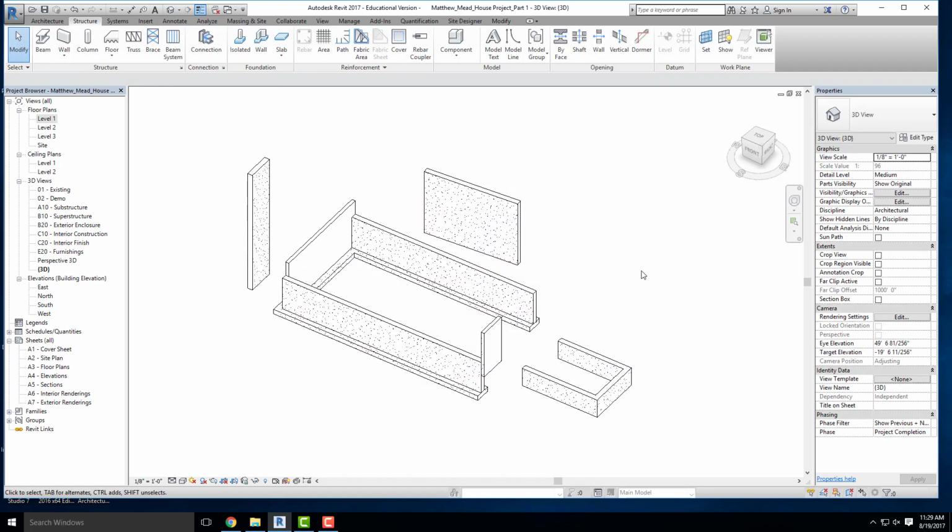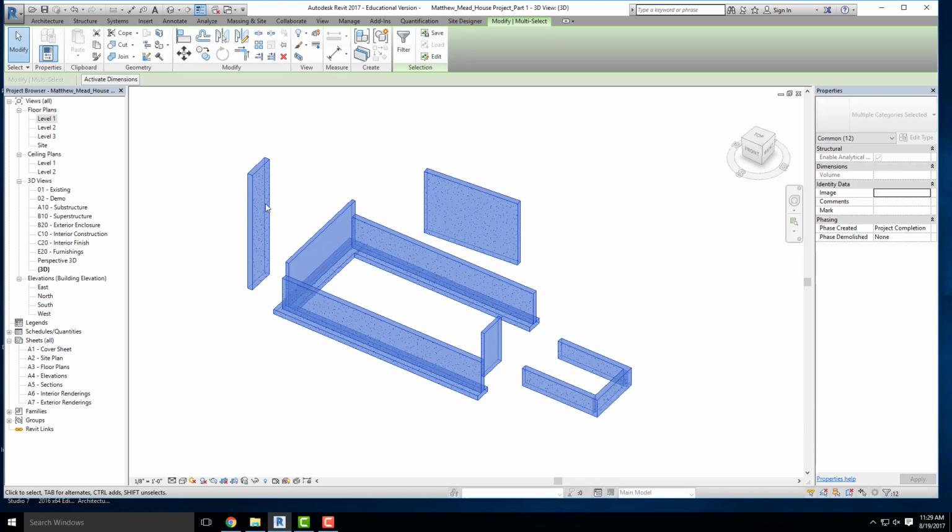Yes, in the back. Where do you find the filter option? So you're not going to see it until you've selected the objects in your scene. So I'm going to select my objects in my scene, and up here in your ribbon, you're going to see a button that says Filter towards the right-hand side. You see that?